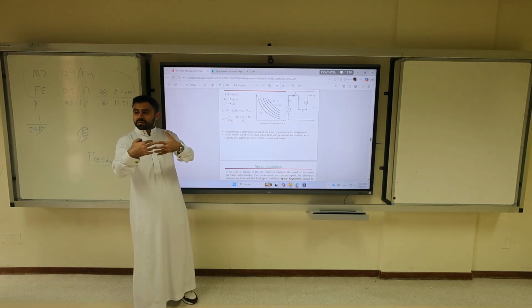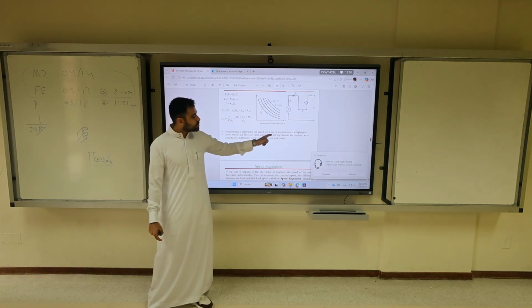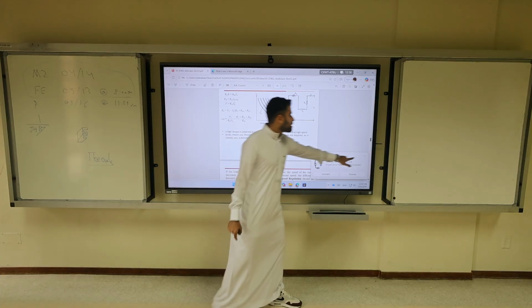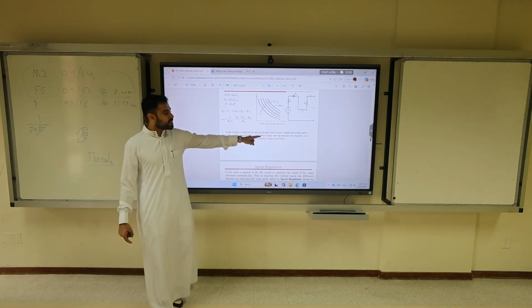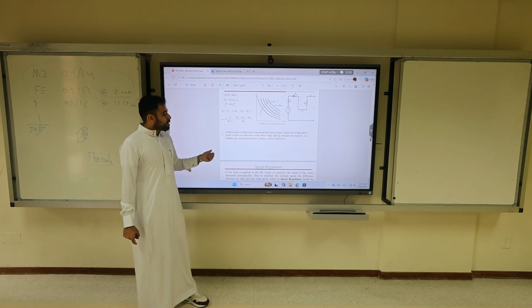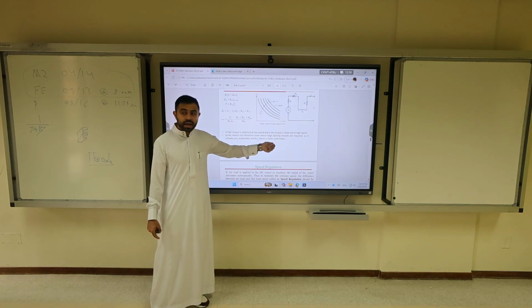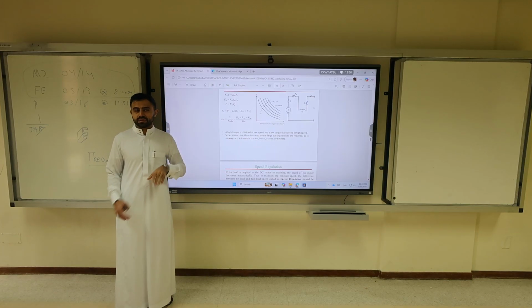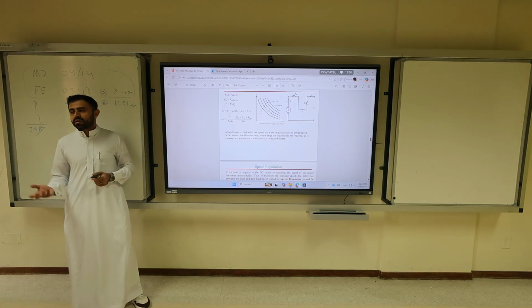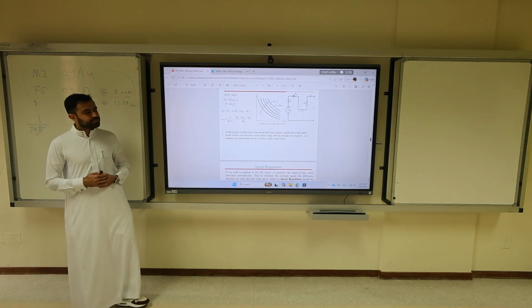So it is interconnected. So a high torque is obtained at low speed and low torque is obtained at a very high speed. Series motors are used for large starting torques. They are used in subway cars, automobile starters, hoists, cranes, mixers, maybe old elevators, but they are not as common as induction. So I think the oil pump is going to be induction because it's more reliable. That's my guess.